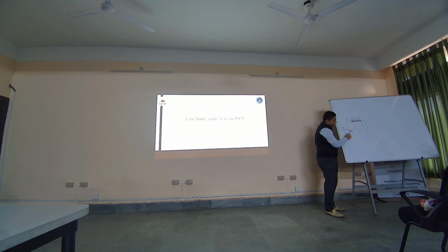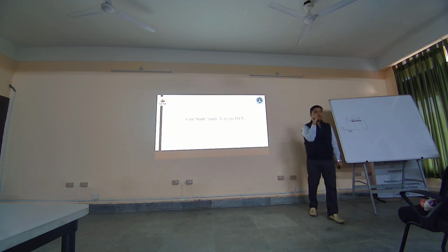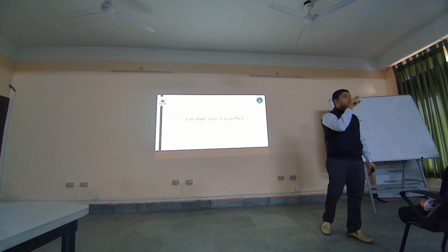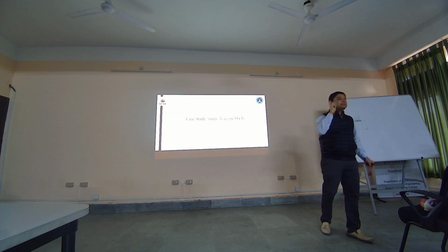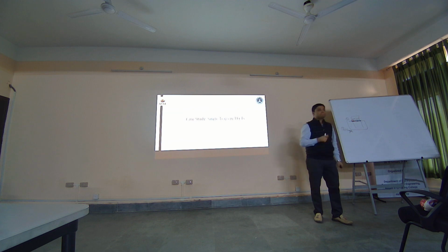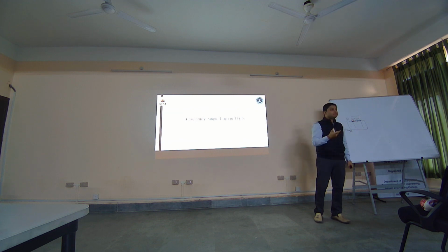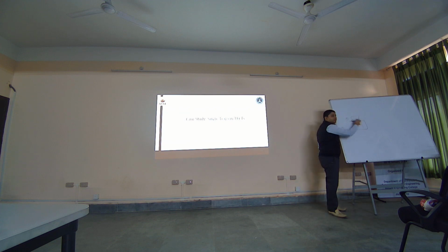So that is the interpretation of this single trap. Single trap allows you to place your trap exactly at the coordinate where you want it in your interface. And that is a very useful tool for understanding the sensitivity of a device. Research on uniform traps has almost achieved saturation. People started in 2011 and now everybody is doing it. But single traps is one area where people are yet to explore.